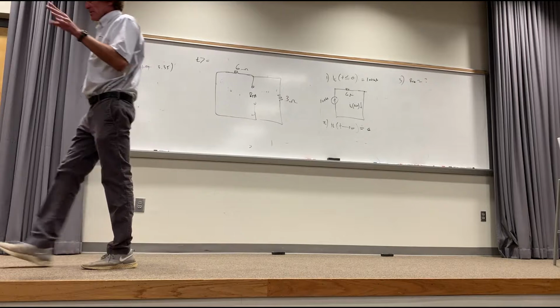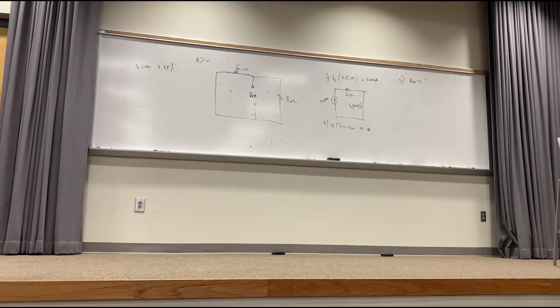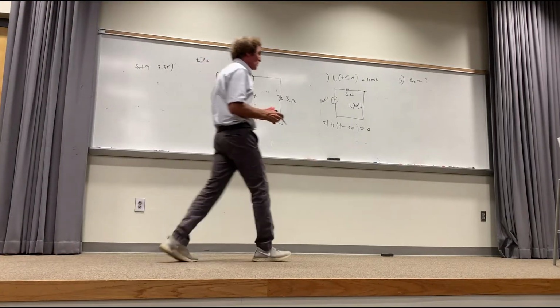Some people say you erase things and don't have time to redraw. Everybody with me on this? That's our Thevenin. How many see that those 2 resistors are parallel? So it's going to be 3 times 6, 18 over 3 plus 6, 9, or 2 ohms. Correct, class? How many see that? It's 2 ohms, so therefore, our Thevenin is 2 ohms.